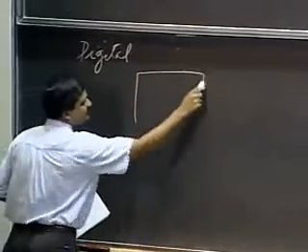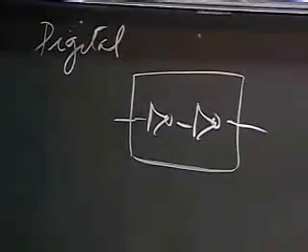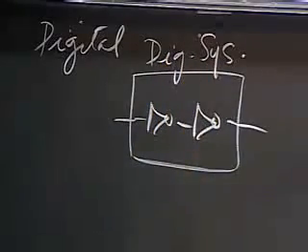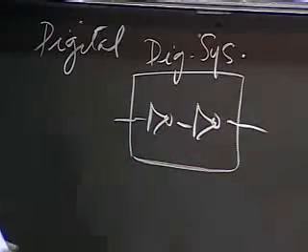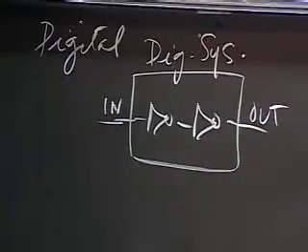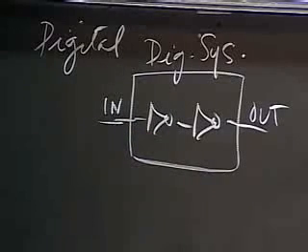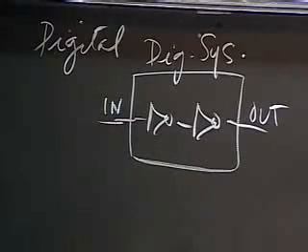So let's suppose I have a very simple digital system. And this system simply contains a pair of inverters. So if I send a 1 here, it's a 0 here and a 1 here. It's a very simple, trivial digital system. And here's the input, here's the output. And we said that for digital systems of this sort to work, they have to follow a static discipline. Our signals and our circuits must follow a discipline for them all to work together.